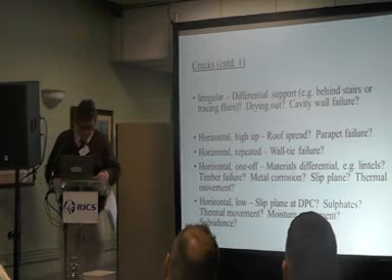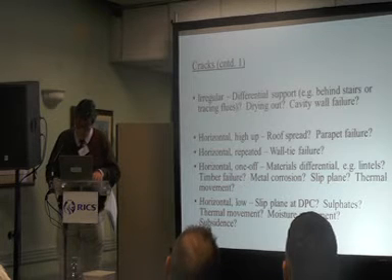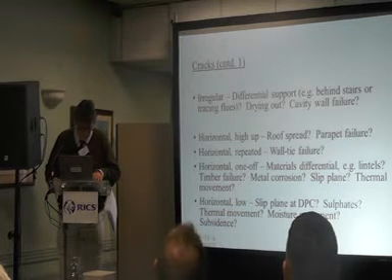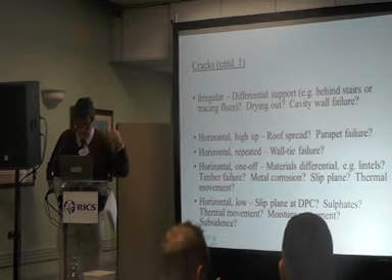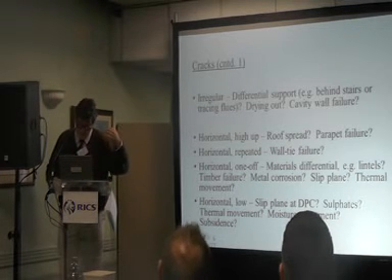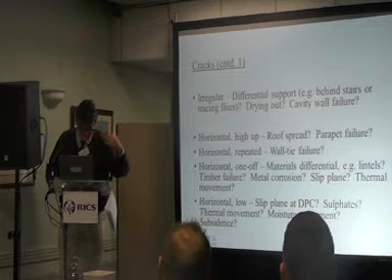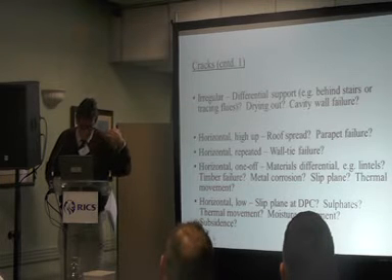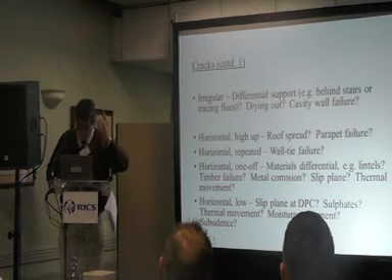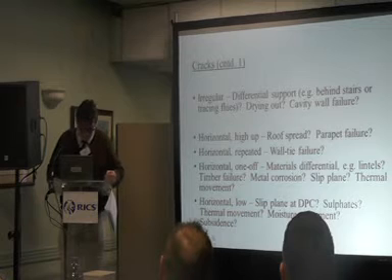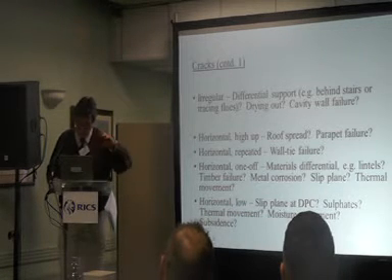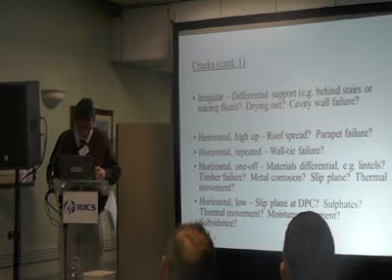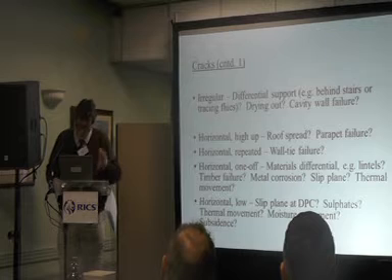Now, where you find irregular cracks, you've got to work hard to find out what the solution is. It could be differential support. So you might find there are stairs giving a little point of support to a building. You could find a crack tracing a flue where there's less support. It could also be drying out cracks. Very often in renders and things you see a lot of irregular cracks which are likely to be drying out. Not so much in heritage property, but irregular cracks are found when you've got cavity wall failure as well.